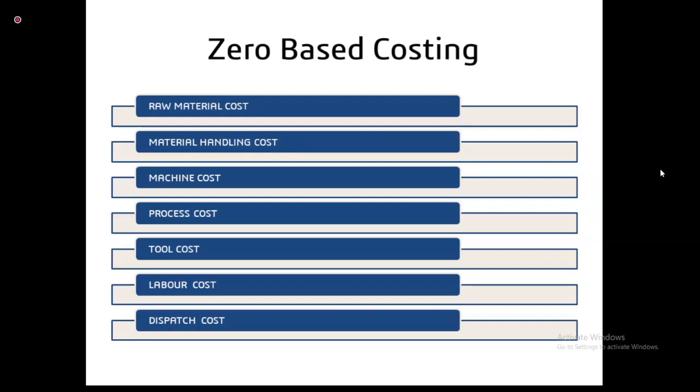Whenever I am doing zero base costing, I have to consider the function and the need of the component and of the product. Say, for example, if I am doing the costing of a shaft, I need to understand the functioning of the shaft. Is any heat treatment process carried out on the shaft, how many RPMs are coming on the shaft, what is the equal mass distribution load on the shaft? Wherever the bearings are going to be mounted on the shaft, should I go with the grinder, or should I just machine it with the help of lathe machines?